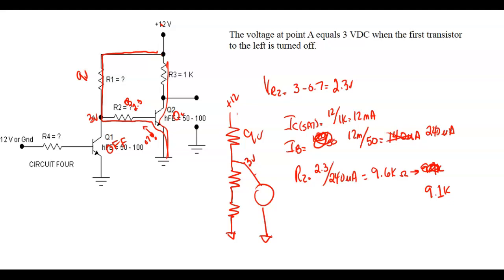So whose law are we using here? We're using Kirchhoff's voltage law, right? So here's a series loop right here, and I know this 12 volts has to be dropped in this loop right here. I know 2 of them. So 9 volts at what current?